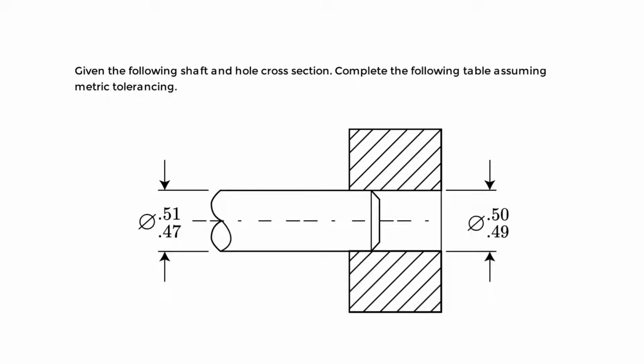But the most important thing, it says in there on that last sentence, the standard specifies the uppercase letters are always referring to the hole. So uppercase letters are for the hole and lowercase letters are always for the shaft. So we have to know that.